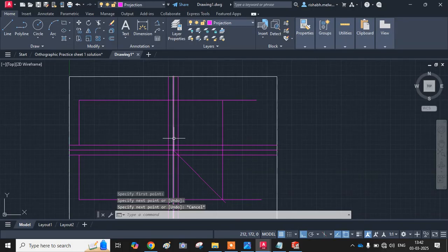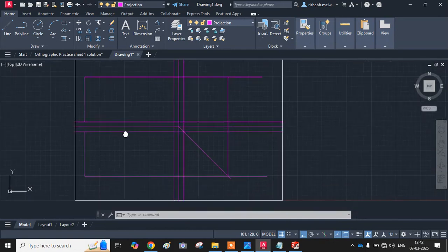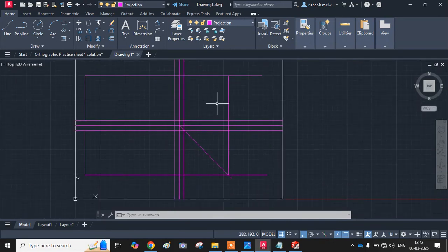So height and width can be taken from the front view and top view. Just to be sure, you can draw this box, draw the 45-degree line and check if it is matching or not. If it is not matching, then the 45 degrees is wrong, and at that moment itself you correct this 45-degree angle so that in the next part of the solution you don't make any mistake. Is it clear?